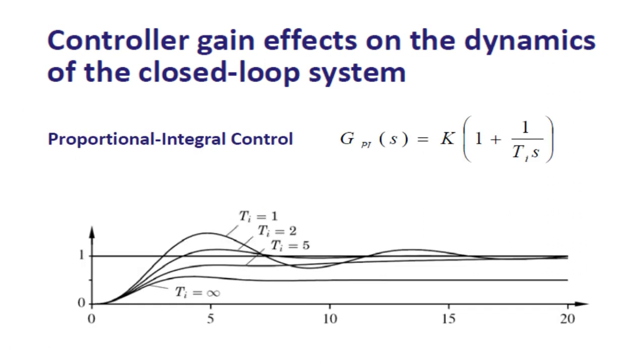Now let's do the same system, but here let's assume a proportional integral control, because when we introduce a constant gain we do have a constant error. So look here, when I didn't introduce anything, we have a gain k of 2, but when we start putting different values of ti, that is the integral gain, look here what happened, it will start removing the steady state error with some oscillation as well.